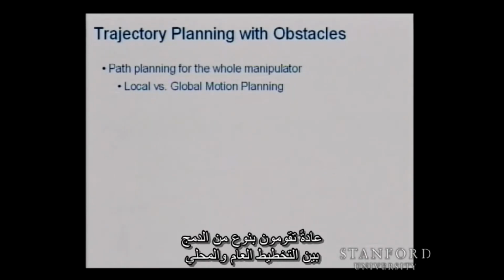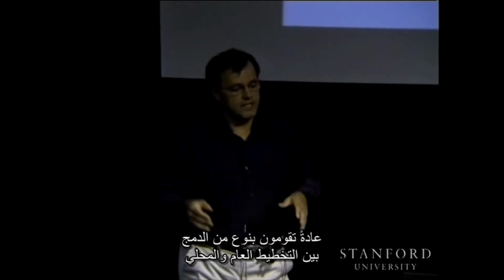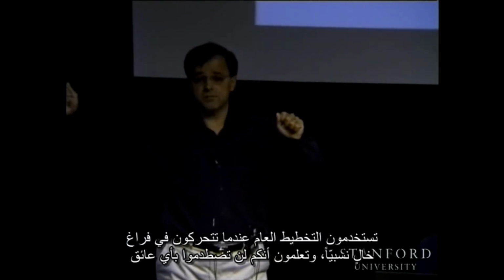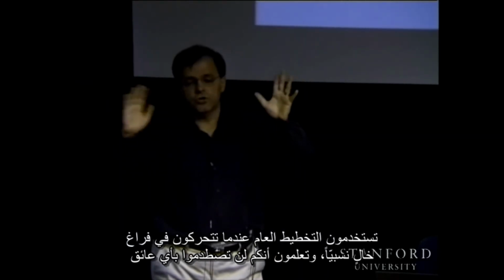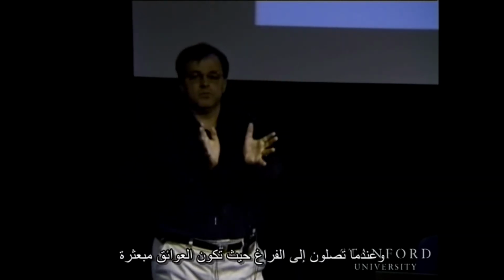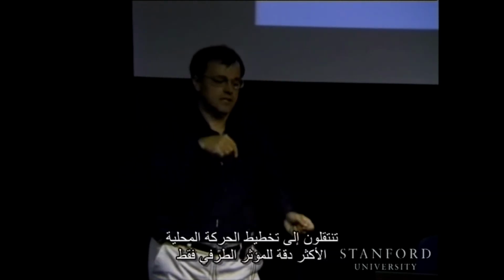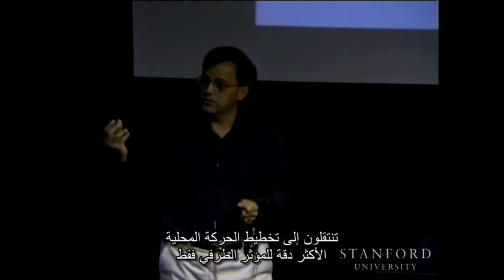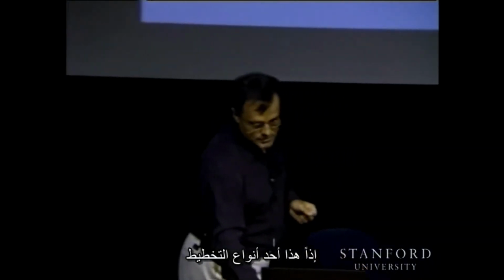So typically you do some sort of a combination between global and local motion planning. You use global motion planning when you're moving through a relatively empty space, and you're not going to be hitting obstacles. And then when you get to the place where it's more cluttered with obstacles, then you switch to a local, more precise motion planning for the end effector only.